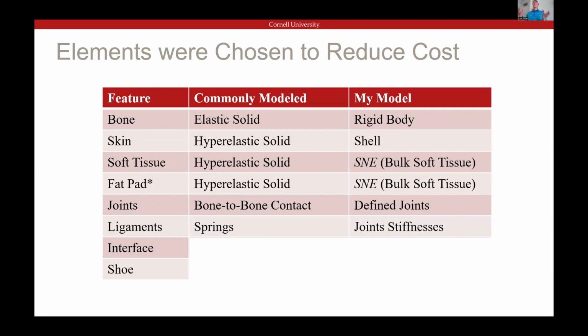And with all these joints being created, ligaments provide the stability to joints. So I'm going to simplify these ligaments. The foot has about 80 ligaments in it. So this would take a really long time to attach if we want to be super patient specific. And it's also difficult to see these ligaments on the MRI once we create this geometry, and I'll go into that. So instead of modeling these ligaments, I'm going to model them as their effective stiffness on the joint.